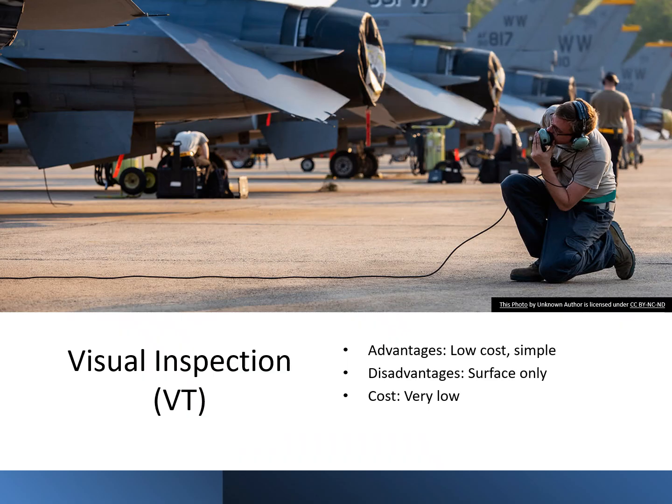Firstly, we have the visual inspection, and the visual inspection is the most fundamental and widely used NDI method. It involves direct observation of a component, often enhanced with tools such as magnifying glasses or borescopes. Its primary advantage lies in extremely low cost and ease of implementation, as it requires minimal equipment and training.